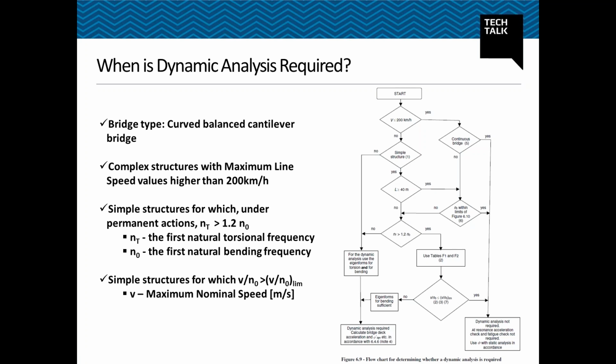Apart from that, you can also refer to the statement from the Eurocode. Eurocode provides some steps for us to decide whether the dynamic analysis is required for your project or not. So engineers can decide whether the dynamic analysis is relevant, based on these algorithms.